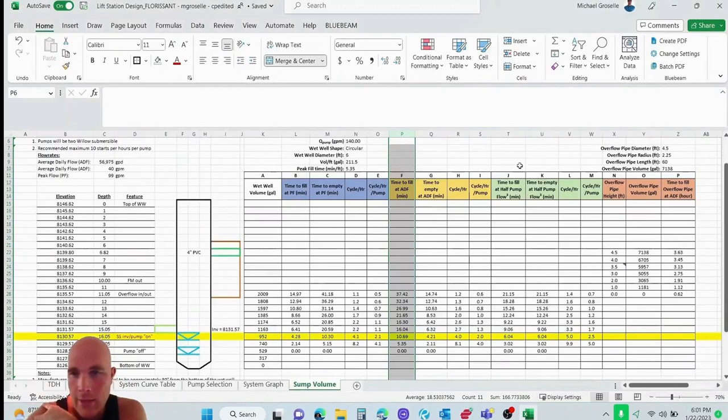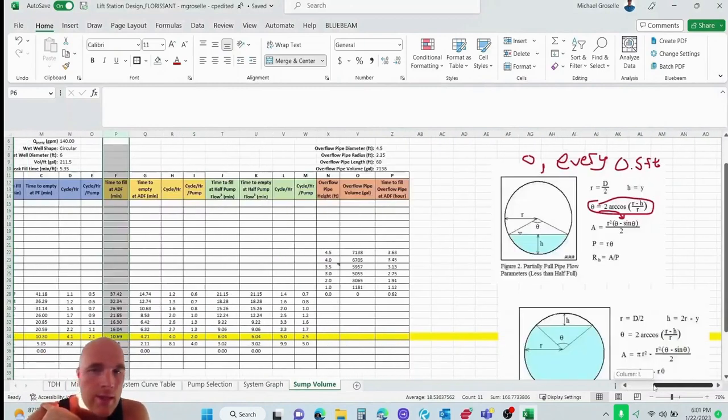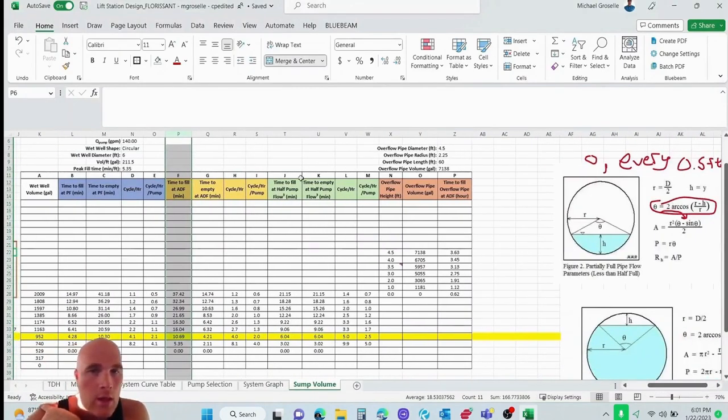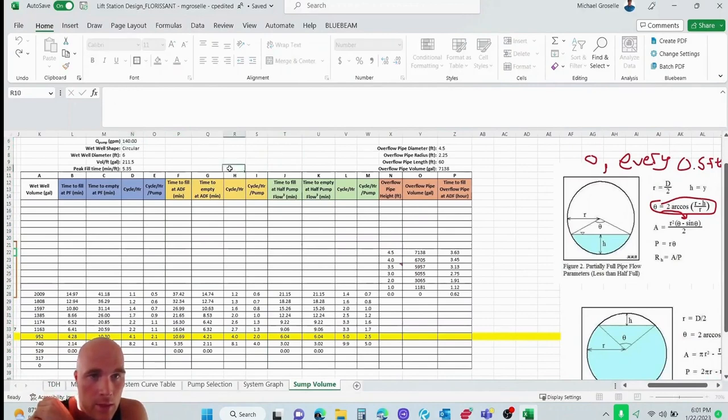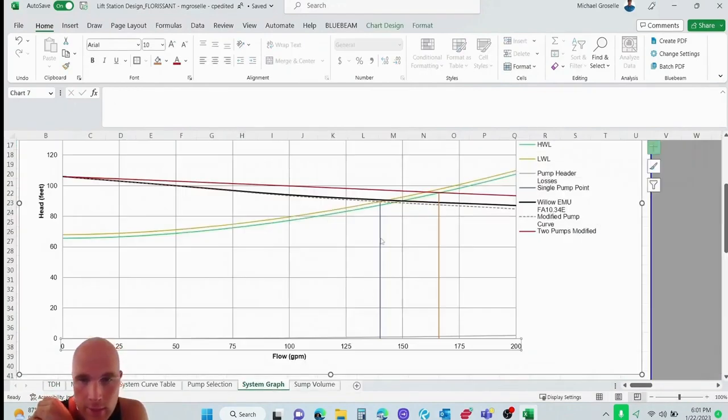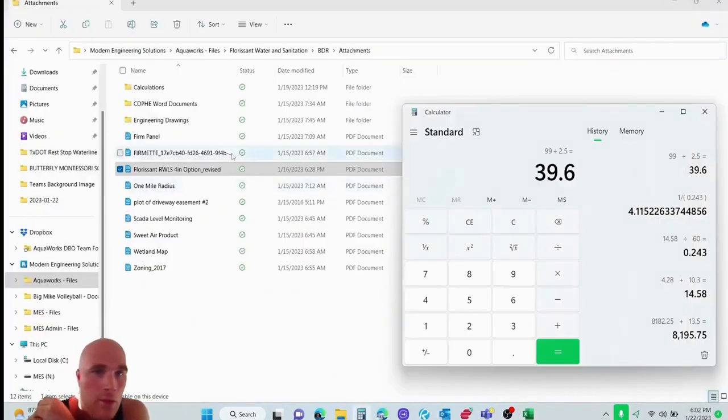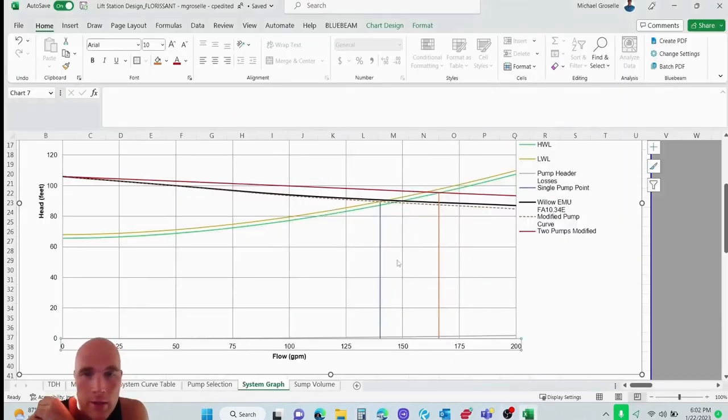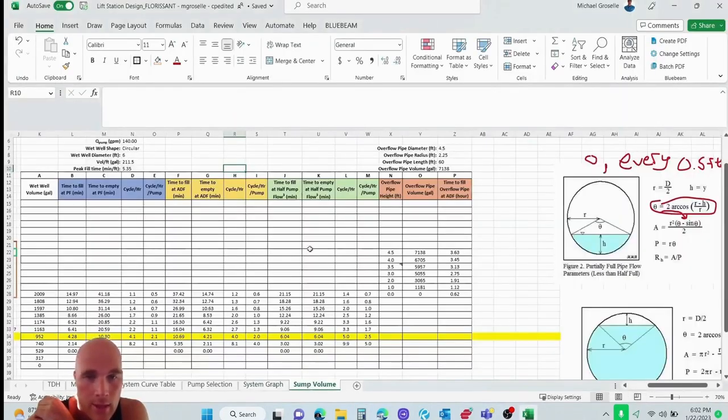So moving on, the average. We're doing the same thing, average daily flow, and then we created this green one here where the pump's critical, if we had a flow that was half the pump. So if we're pumping 140, which is what we have here, the critical pumping is at 70 GPM coming in. So what happens if we're at 70 GPM? How many cycles are we going to get? 2.5 per pump, or 5 if the alternator is broken. So all these numbers are below 10.